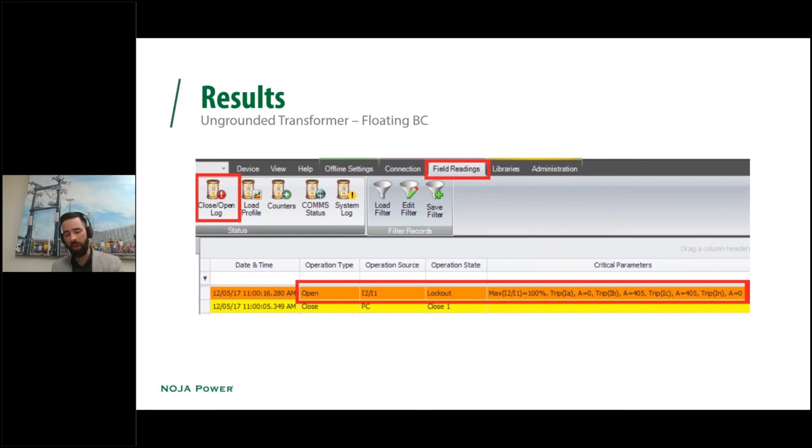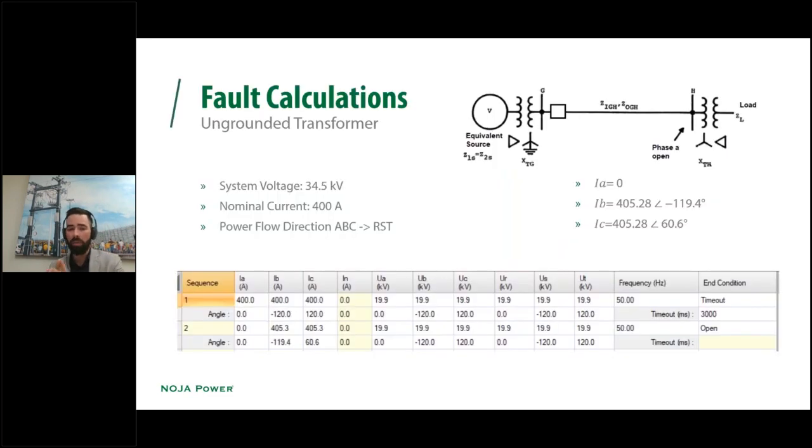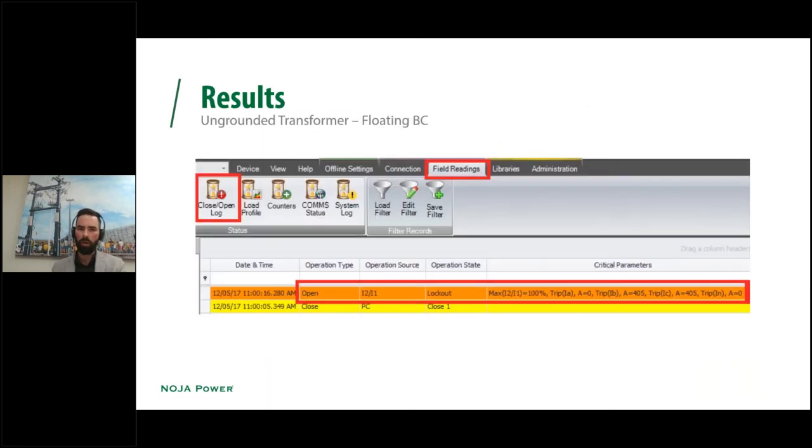So again, you're able to detect the scenario, and very clearly in this case, if you didn't have negative phase sequence or broken conductor protection, you're not going to pick this up on overcurrent, and you're definitely not going to see it on neutral overcurrent either, your earth fault protection. So it does help you address a blind spot in your protection calculations or in your protection schemes to identify these broken conductor faults.